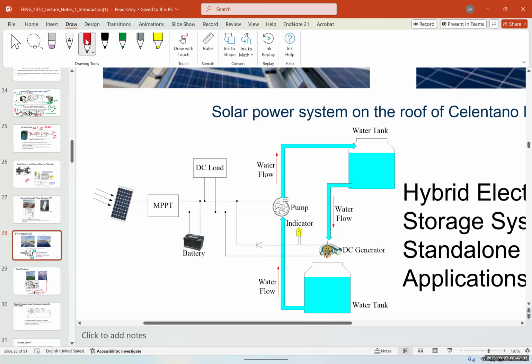The excess power, you can use to pump water and store it in the upper level tank. At night, when you don't have solar power, you can just release that water through a generator and create electric power. This is not very efficient. The efficiency is around 60-70% max, but it's very cheap. Especially if you're on a foothill or you have an elevation, you can easily and cheaply generate power.